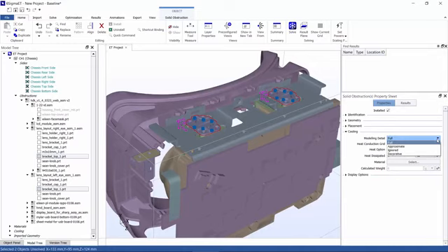Full will add grid to capture features in detail and will add grid to the model. Approximate uses the grid generated by other objects to grid the object. So use this option only on objects that you know are not thermally relevant to the model. Ignored and decorative remove the object from the thermal simulation and all environmental calculations. So these are the options you have available. Typically, we just use approximate. You can select that. And when you go to grid this model, now it will do a more rough job of capturing it.